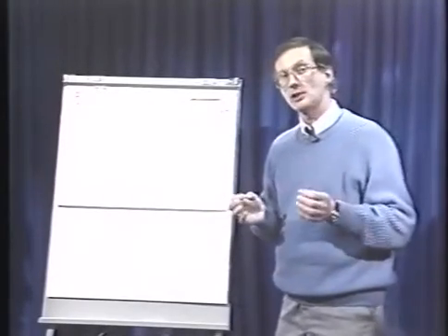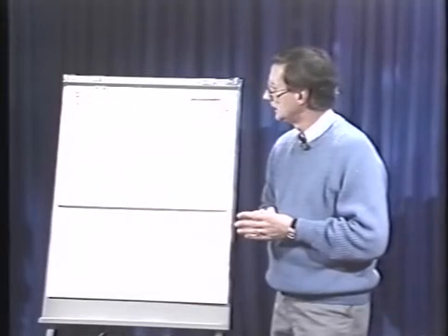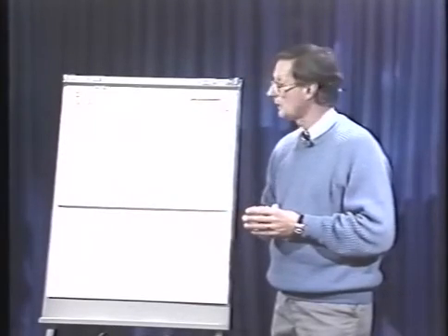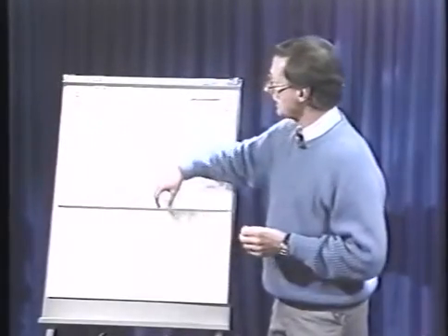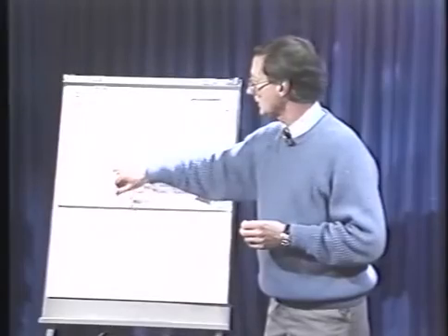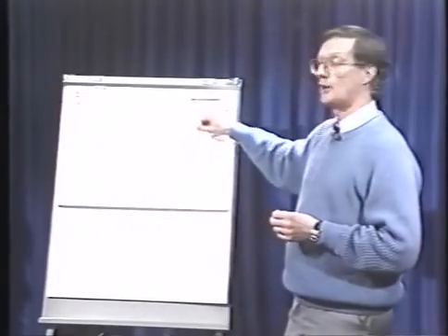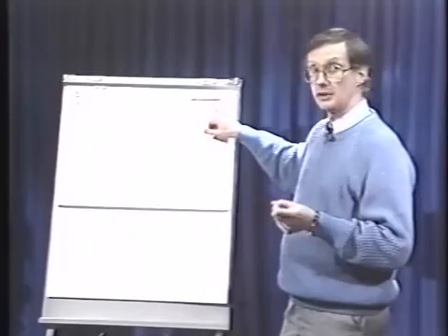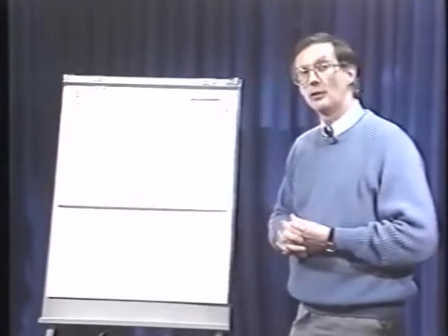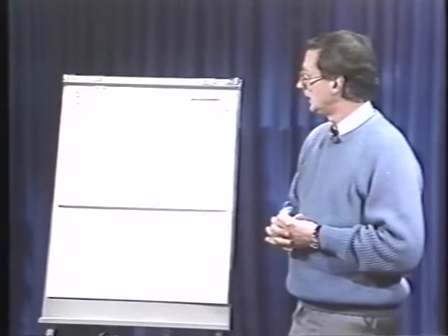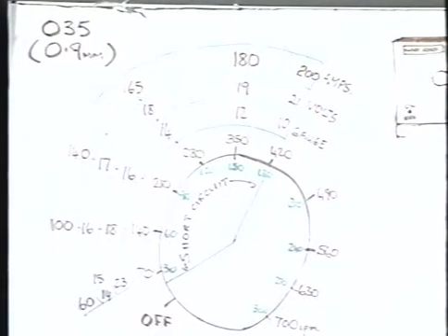So on a simple sketch like this, we can now determine a lot of data for short circuit welding. We can determine the current range, 60 to 200 amps, is traditionally found at the 7 o'clock to 1 o'clock position on a normal wire feeder. If you have a digital wire feeder, then it would be between 70 inches a minute and 420 IPM. We can also see on this simple chart the voltage requirements for short circuit welding, 14 volts to 21 volts.